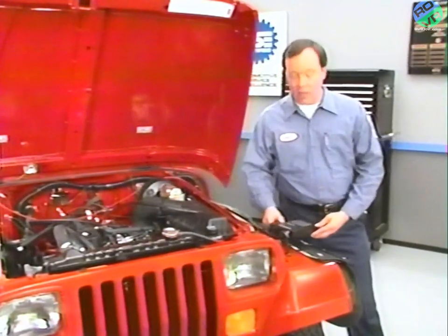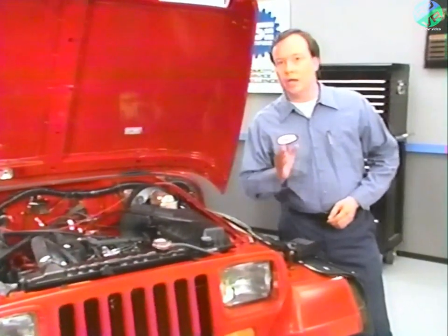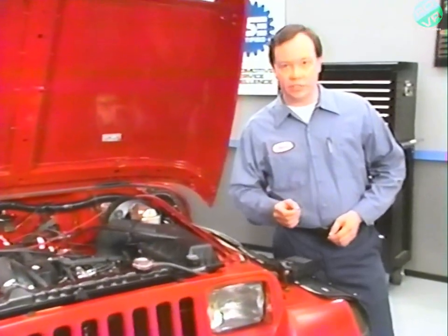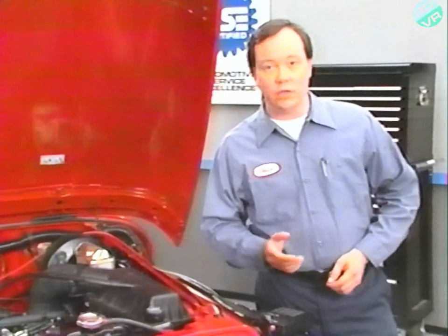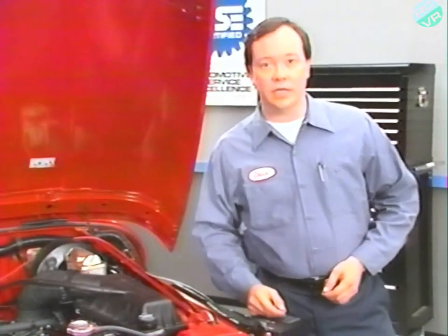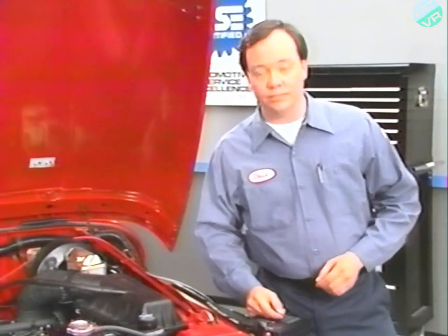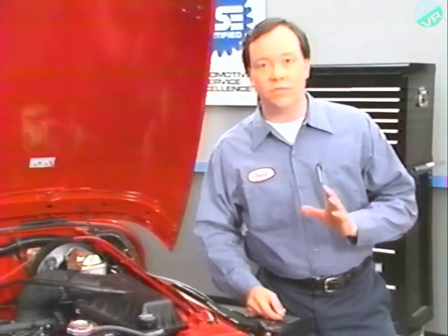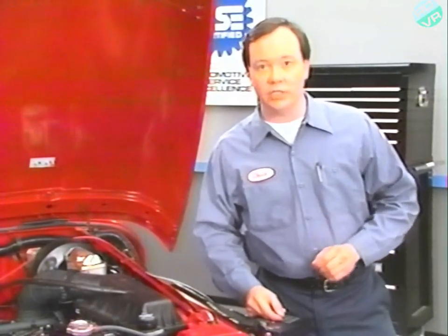Well, now that you understand how faults are set and how to access them, let's take a look at a few sample conditions that involve troubleshooting fuel injection system faults using the DRBII and the 1991 Powertrain Diagnostic Manual. We'll be using a Wrangler for our first problem, a no-start condition with a fault message. We'll start with test NS1A in the Powertrain Diagnostic Manual.